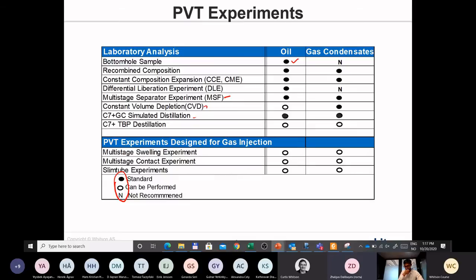It doesn't matter if we need to know the composition in the reservoir or inside the well, because in the well there are different processes, like fluid segregation, and so on. Just CVD, right? Yeah. So if you're talking about in the wellbore, then I would just take the CVD removed equilibrium gas, and flash that at pressures and temperatures within the wellbore. That would give you the liquid dropping out at a little bit lower temperature or pressure.